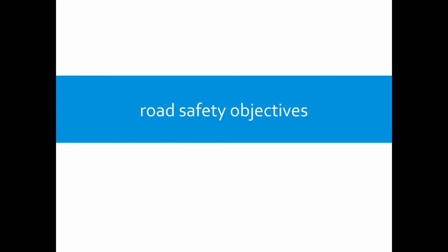More specifically, I suggest adopting the following safety objectives when a road is designed. First of all, separate potential conflict points and reduce potential conflict areas. Control the relative speed of the conflicting vehicles. Guide the driver through unusual sections. Ensure that the needs of pedestrians and cyclists, if relevant, are taken into account.